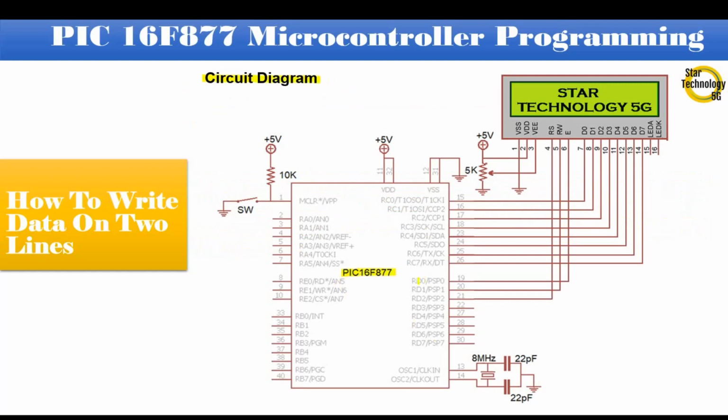It is the PIC16F877 microcontroller. Pin number 1 is master reset. If we press the switch it will reset the microcontroller. Port C is interfaced with LCD data pins. Here is the LCD. We are using a 16 by 2 character LCD. Its data pins D0 to D7 are interfaced with port C of the microcontroller. Pin RD0 is interfaced with EN pin. Pin RD1 is interfaced with RW pin. Pin RD2 is interfaced with RS pin.